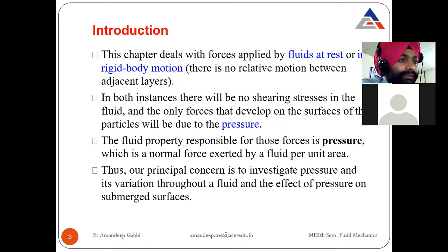In both instances, there will be no shearing stresses in the fluid, and the only forces that develop on the surface of the particle will be due to the pressure. So there will be no movement of the fluid, no shearing stresses in the fluid. That is, we will not consider viscosity anywhere. We will consider pressure. The fluid property responsible for those forces is pressure, which is the normal force exerted by the fluid per unit area. Thus, our principal concern is to investigate pressure and its variation throughout a fluid, and the effect of pressure on submerged surfaces.